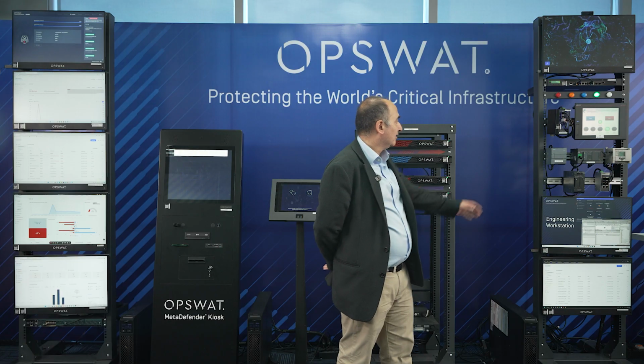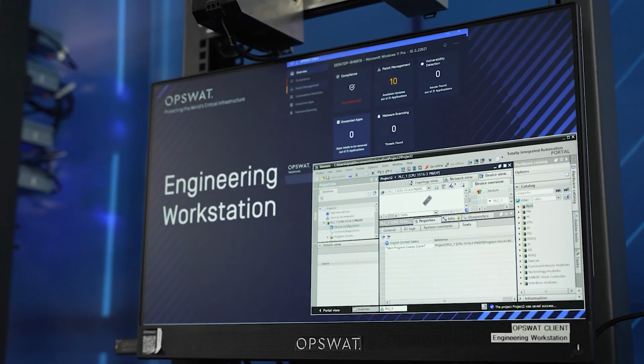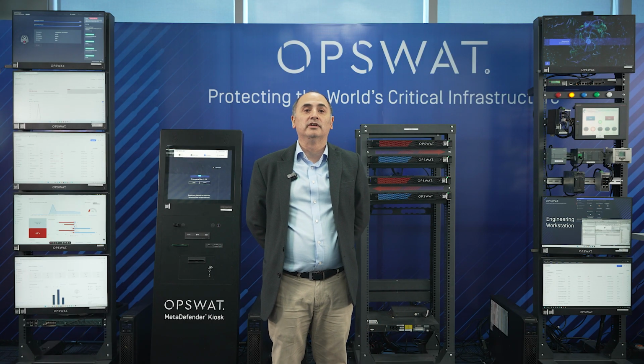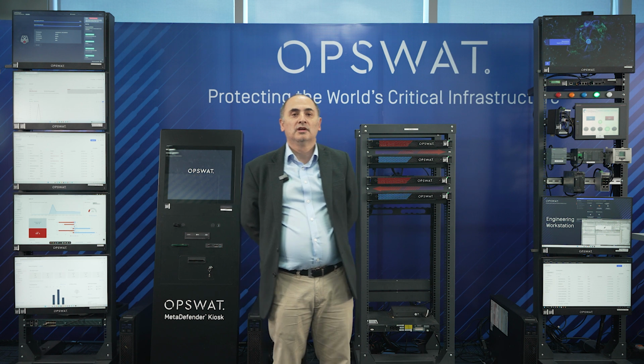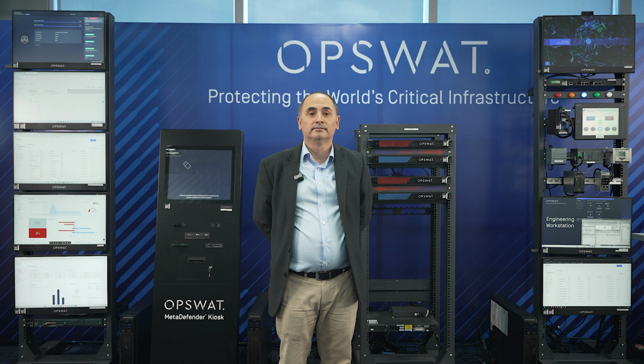On the OT side, I've got some PLCs, I've got my HMI, I've got my engineering workstation, and I've got other key applications such as historians. Some of the challenges on this infrastructure is we've got different applications from different vendors, we've got different protocols used by these applications, and the key thing is the systems have to be up and running, so availability is key. A lot of the tools that are used by IT security do not work in this environment.